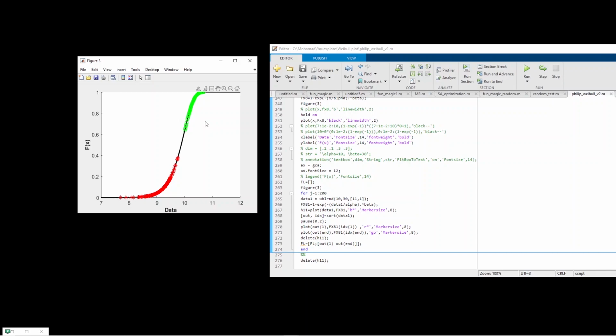So if I want to assign a probability of failure to the first point, the most logical thing that I can do is to consider this distribution, calculate the median of this distribution, and assign this median to my first sample. That's why we call it median rank. So we calculate the median of this, and that probability will be assigned for the first sample. We calculate the median of the second distribution and assign that to the second sample, and so on for the last data point. So we calculate the median of this and assign it to the last data point.